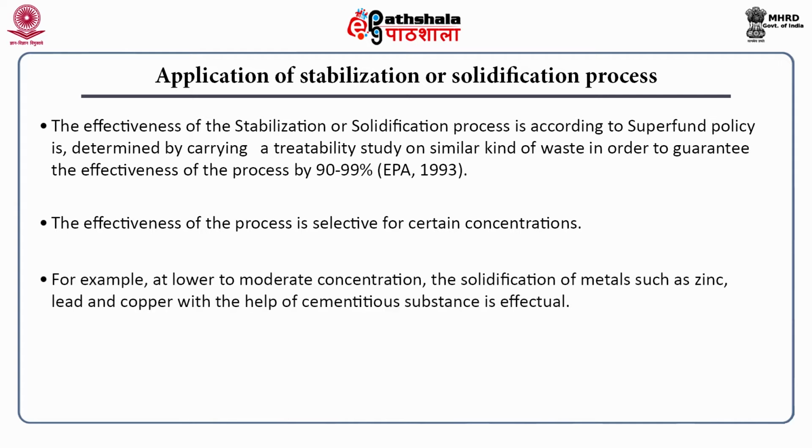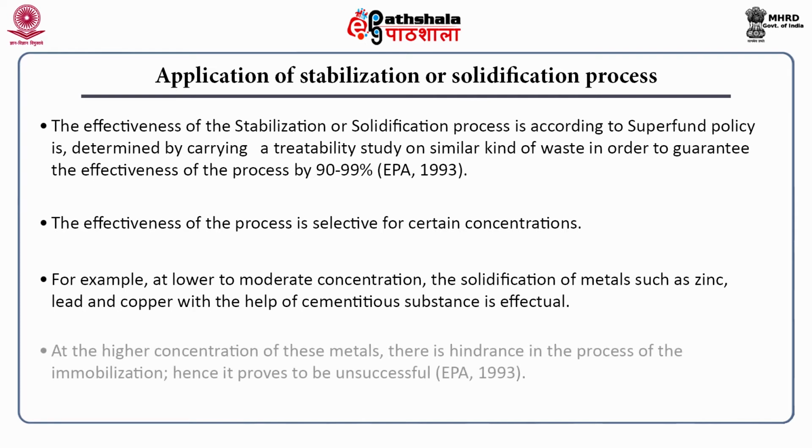For example, at lower to moderate concentrations, the solidification of metals such as zinc, lead and copper with the help of cementitious substances is effectual. At higher concentrations of these metals, there is hindrance in the process of immobilization. Hence, it proves to be unsuccessful. This is according to EPA 1993.